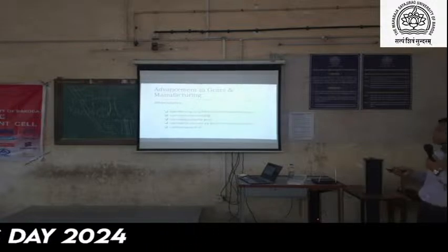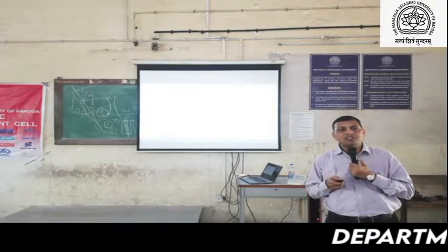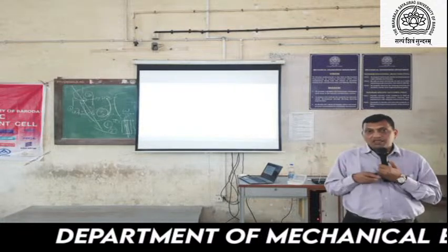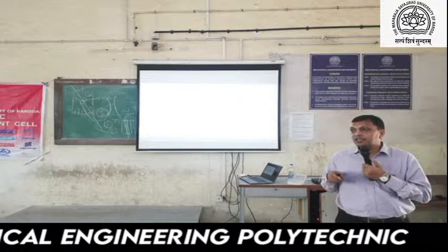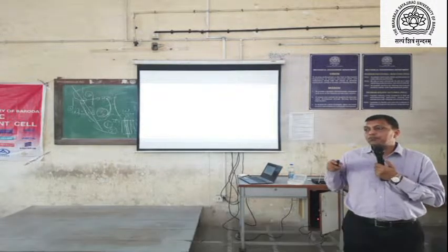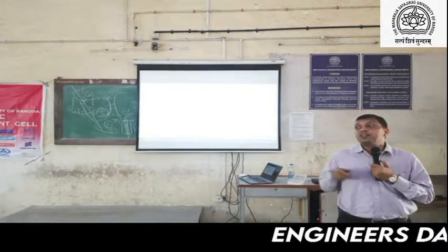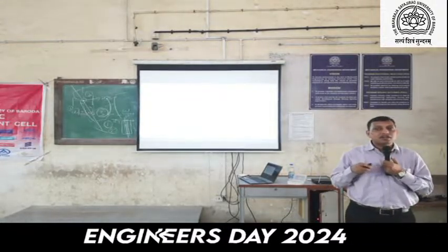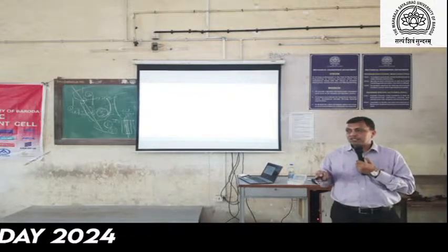Then optimize with reference to dynamic behavior. Dynamic behavior means some applications do not continuously take the same type of load in the same cycle. It should be variable in some cases, and based on that we can optimize our design. If we directly define that in 1 minute the peak load is only for 10 seconds, and we consider the 60 seconds for our design, then the design would be higher, safer, and costly.